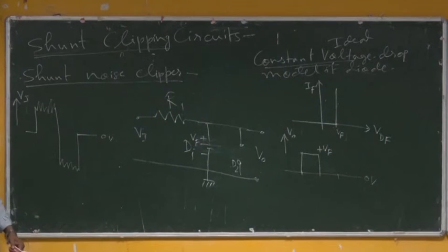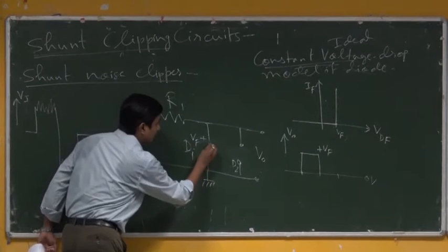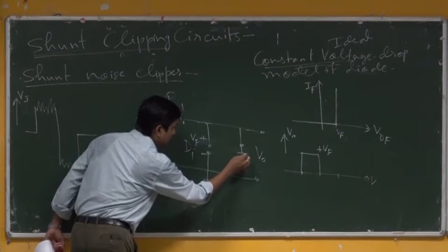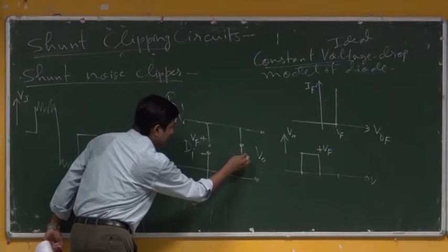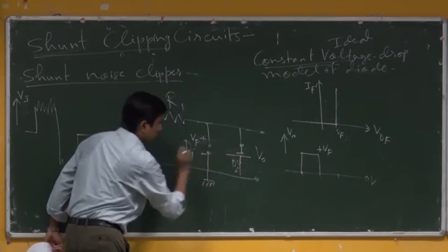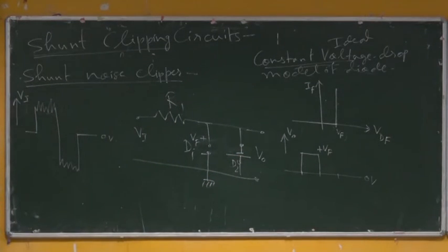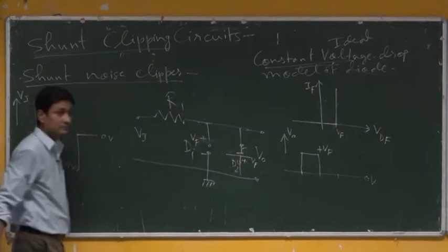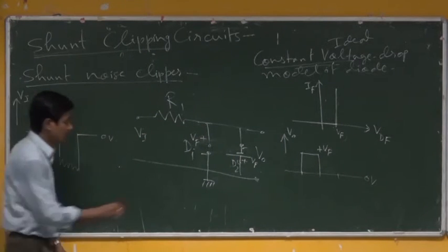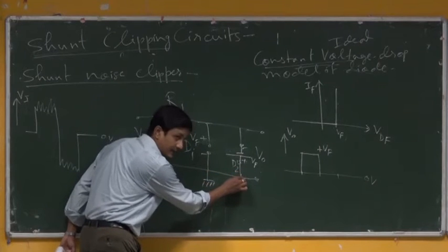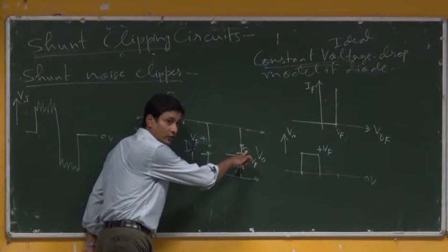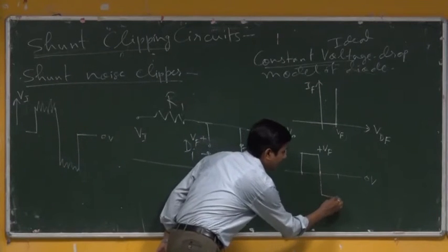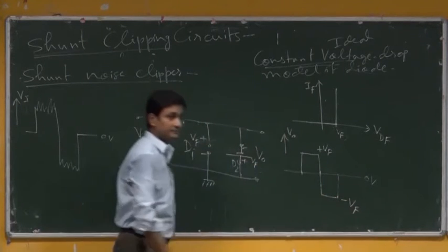Similarly, I can revert the other way. I will make one open and the other conducting, with negative here, positive here. I think this way the diode was connected, P side the other way, but the potential is again Vf. But with respect to ground, this is the reference point which is 0 volt there. With respect to this, this one is Vf volt that I found from here, but it is a negative voltage. So, I will get a negative Vf there.